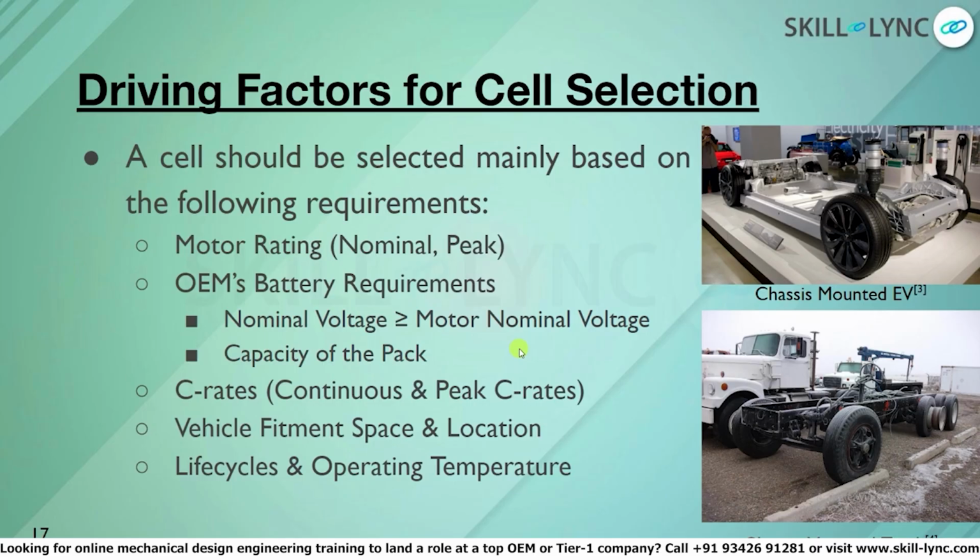Remember, it's not just the cells that you'll have in a battery pack. You'll have a lot of other components, like cooling plates, the BMS, and contactors, switching gear to protect the battery pack from high currents and high inrush currents. You'll have wiring lines, voltage sensors, current sensors, power contactors, etc. So it's important to consider all those things, and then decide on the cell, so that you have a proper vehicle fitment when the whole battery pack has been designed.